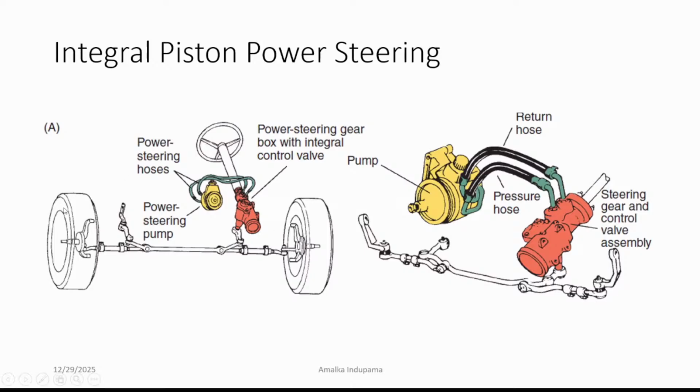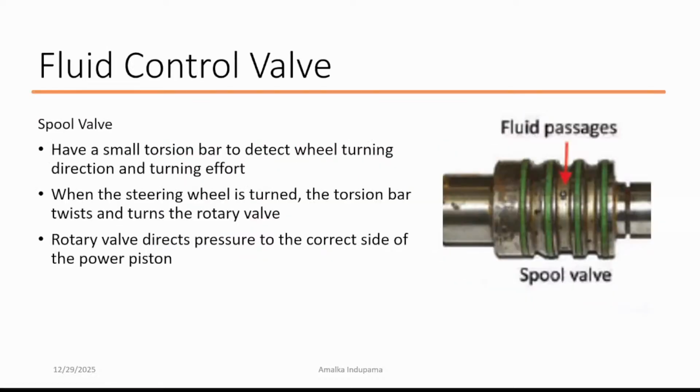Yes, here is another figure that shows the integral piston power steering system. So we don't have any rack and pinion there. All the work is done inside the steering gearbox.